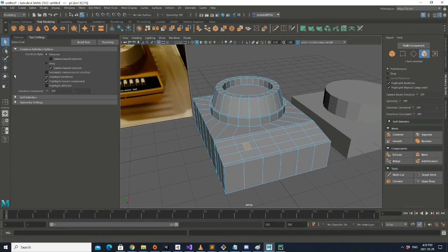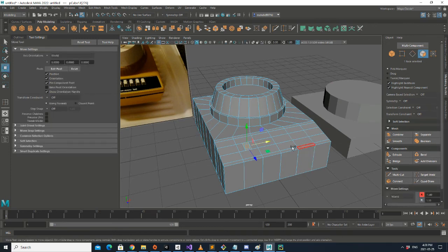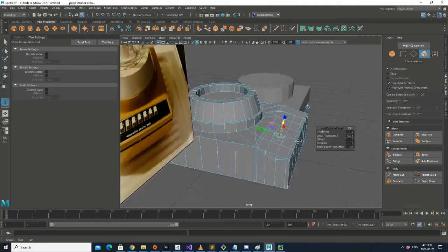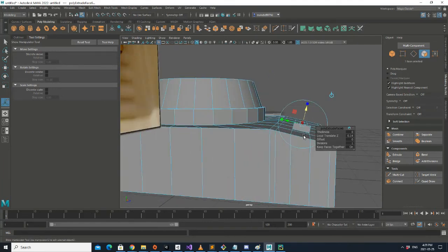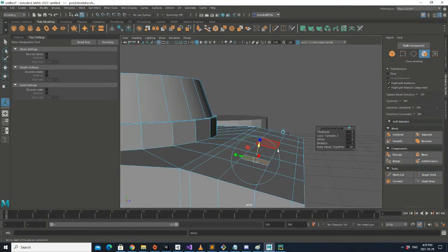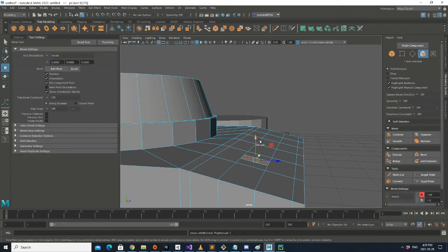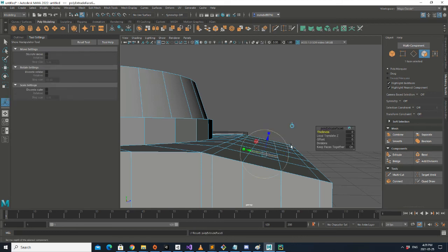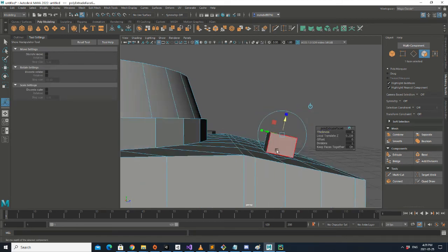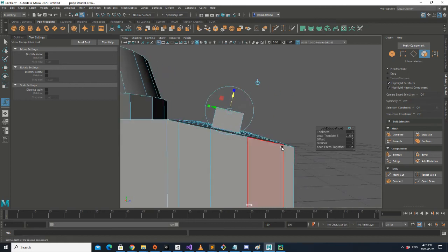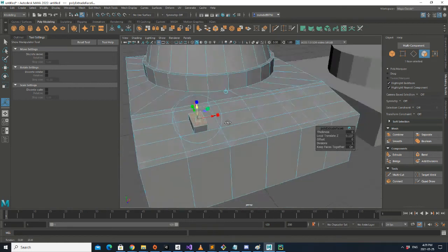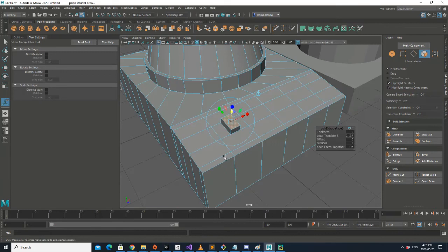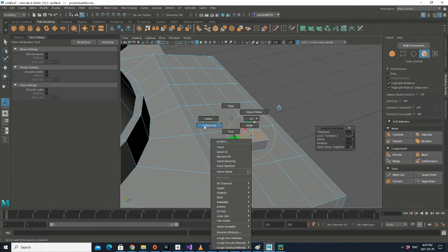And now what I'm going to do is to extrude it, and using the extrude tool there is better because it's just going to follow the normal on that surface. Let me show you what would happen if you just use the extrude here. It will go completely upward here, but if you use the extrude there, it will give you the arrows based on the normal of this surface. And normal, I think you know, but let me just say, is a vector perpendicular to this surface.